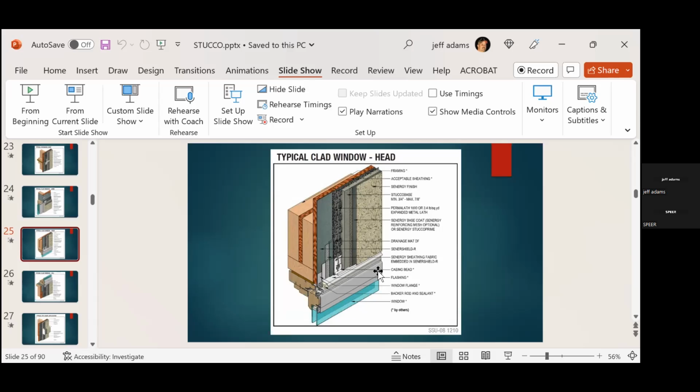But in this case, they're doing the flashing and then they're doing a plaster stop on top of that, which is a great way to do it. You do have to watch it. If that plaster stop curves up on the end, it creates an issue for ice damming, especially as you go northward. But it does occasionally happen here. If it ice dams, it just completely fractures. It forces that moisture up the wall, obviously damages it, the plaster everywhere. So it cannot have that turned up lip if you're going to do something like that. So one of the simplest ways is to go ahead and put your head flashings on and then just do a weep screed here, and that'll solve a lot of that problem.